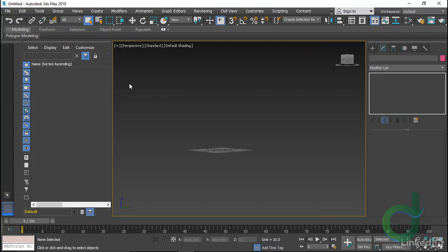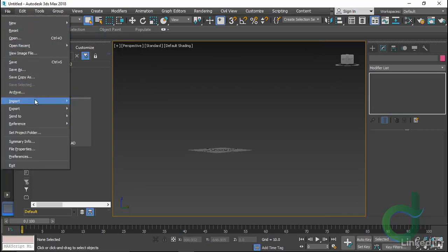I've made a new scene, and I'm going to do something different, choosing File and Import. And now instead of linking, I'll import the FBX. Here's why. In the link, I've preserved everything as unique, figuring I'm going to adjust things back in Revit and update the link. However, I want to adjust things here in 3ds Max and see those changes propagate. At some point, you may decide that you don't want to round trip to Revit for the alterations you're making. You're using 3ds Max either for cleanup and real-time simulation transfer, or to do a render, and it's not going to go back to Revit as a model.